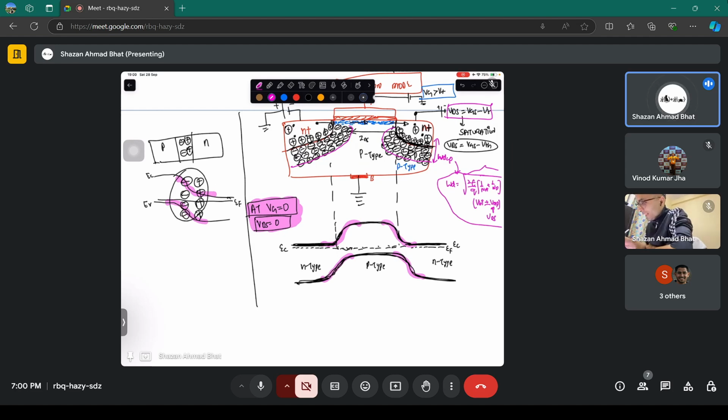So this depletion region is present also here. It's present throughout. It does not discriminate. So it occupies part of the channel also. You see, now part of the channel is occupied with these immobile negative and positive ions from the depletion region.